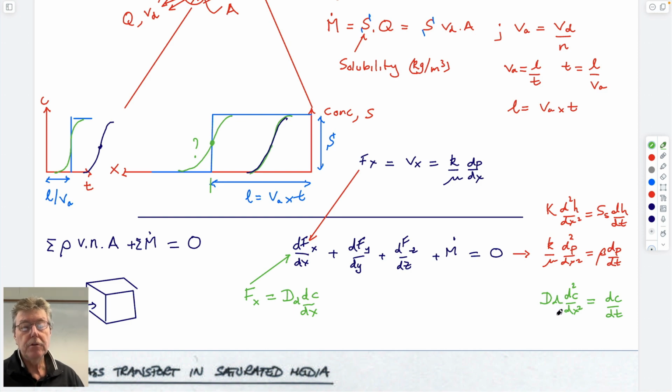For mass transport, this says that any mass that comes in dissolved within the water that flows into this system either flows out the other side or accumulates. And so this is the balance equation, mass in equals mass out. And what doesn't balance is an accumulation, ACC.